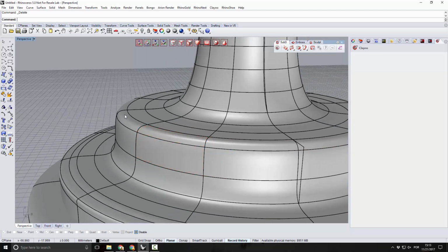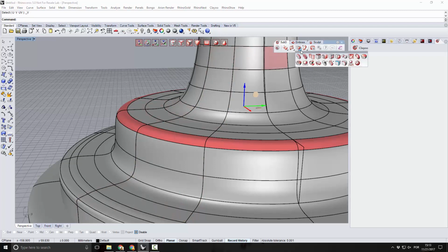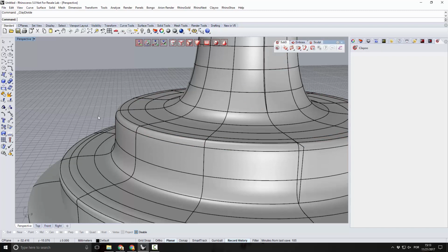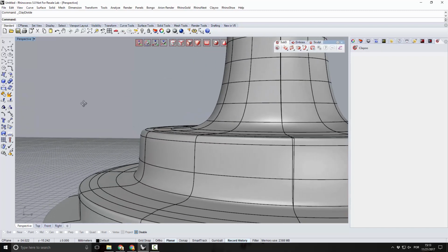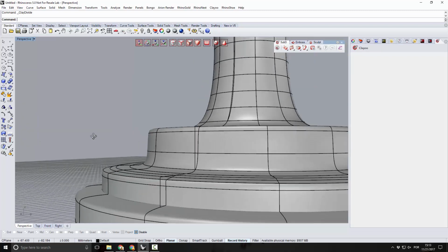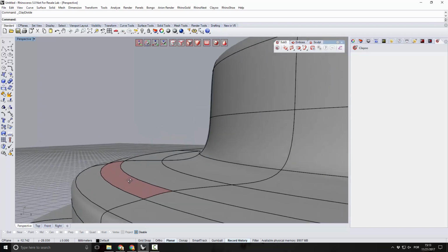Just select the loop of faces to divide. Let me probably pick the selection loop, in this case not this direction. Let me click again the other direction, and just with this extra division, just with the divide, we get this more sharp edge also in here.